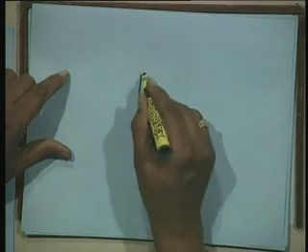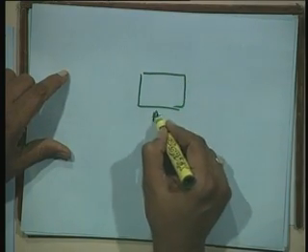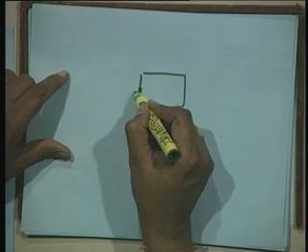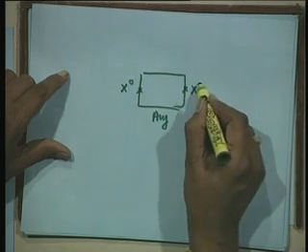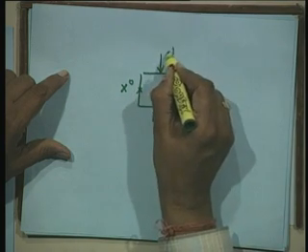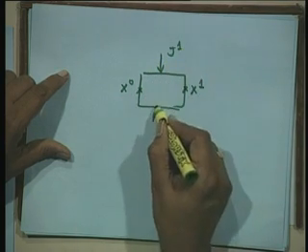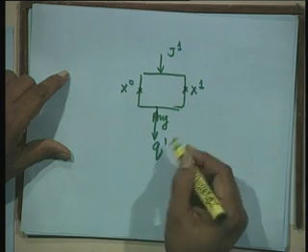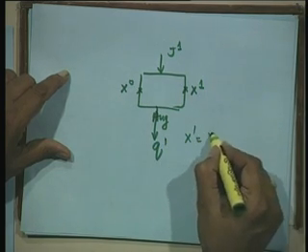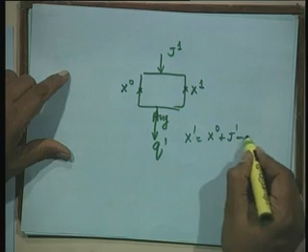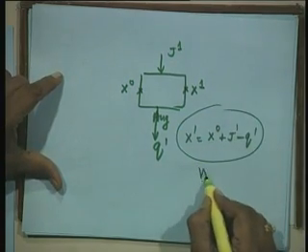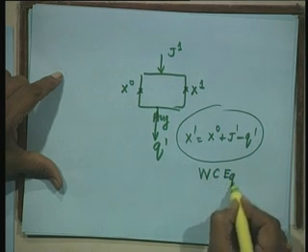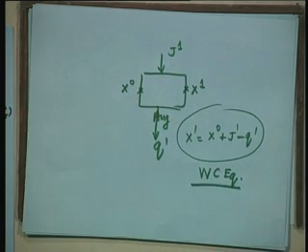This is the reservoir. Let us say month of August. In the beginning of August, this is the water storage. The end of August, this is the water storage. During August, this is the inflow, and outflow or discharge is Q1. So, X1 is equal to X0 plus input minus output. This is called water continuity equation, which you must have done in control system, plant equation.